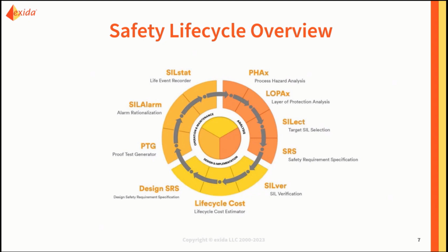For IPLs that are safety instrumented functions, you would be able to determine the target risk reduction factor and target safety integrity level in the SIL selection tool. This can be done using your LOPA results, using risk matrix methodology or risk graph methodology.